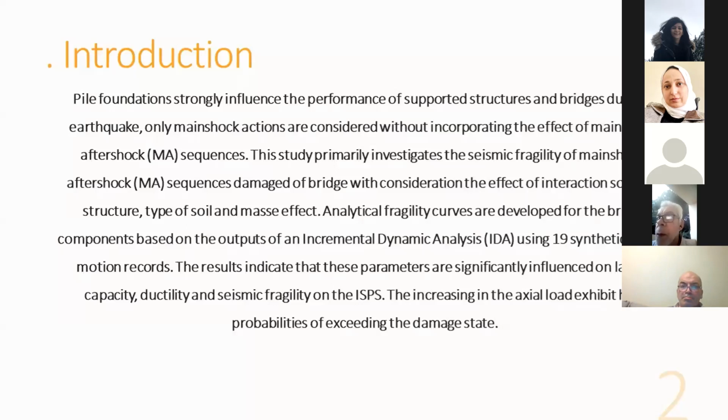Introduction. Pile foundations strongly influence the performance of supported structures and bridges during an earthquake. Usually only main shock actions are considered, without incorporating the effect of main shock aftershock (MA) sequences. This study primarily investigates the seismic fragility of bridges damaged by main shock aftershock (MA) sequences, with consideration of the effect of soil pile structure interaction, type of soil and mass effect.